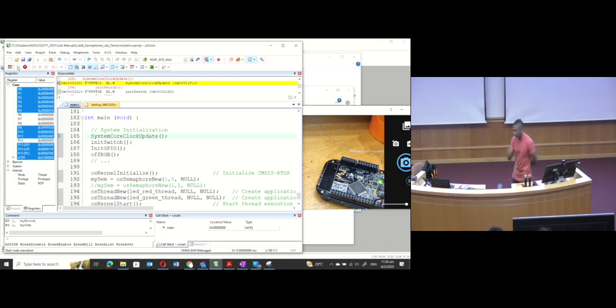Now if I press very fast, what happens? Red and green, do you see? If I press very fast, it will become green then red. That means when green releases and is still running, I release again, so red can also unblock. So this is a way of synchronizing or controlling when some task should run.